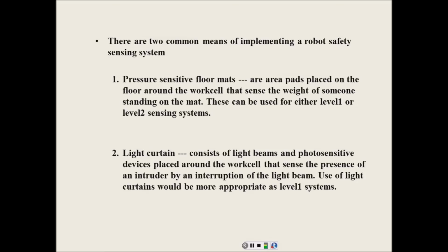If you're in an environment where you go from hot to cold and you have condensation, that'll cause you problems with your light curtains. Pressure mats don't have that problem. But light curtains can cover a lot of space. We can have basically one set of transmitters and one set of receivers and then bounce it around the outside with mirrors. And we can protect the whole space and still have the space be open.